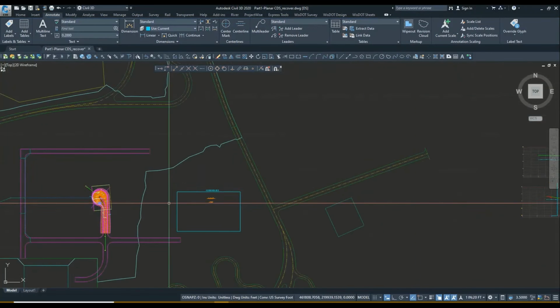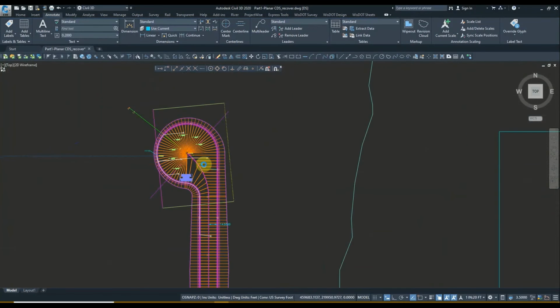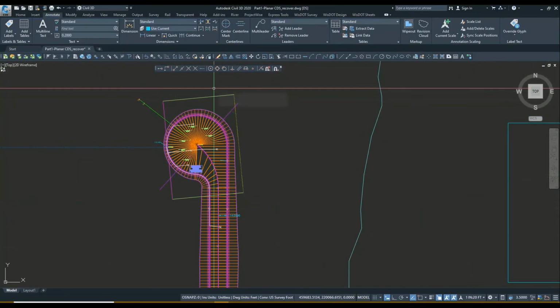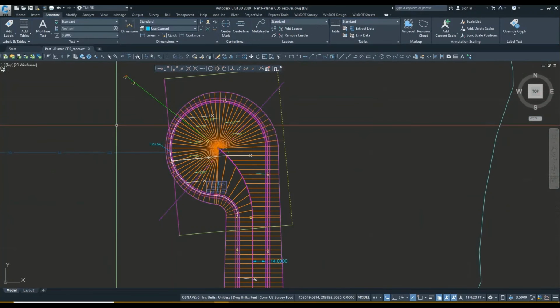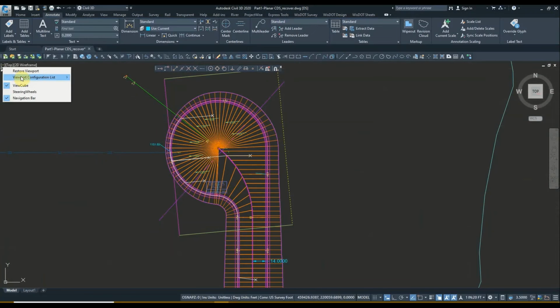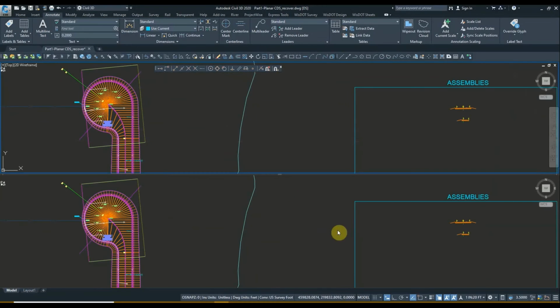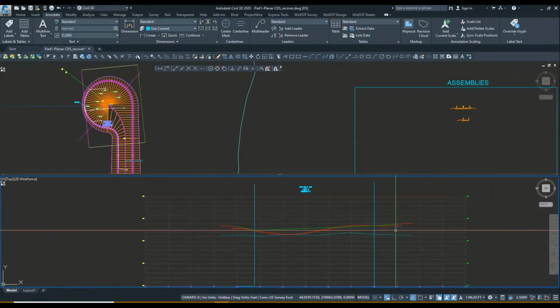And like I was saying before, this feature line, since it controls the setup surface, makes the whole thing very dynamic. So what I can do right now is I can go ahead and change the low point elevation, and we should be able to update everything really quick.